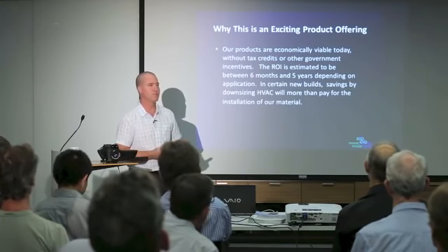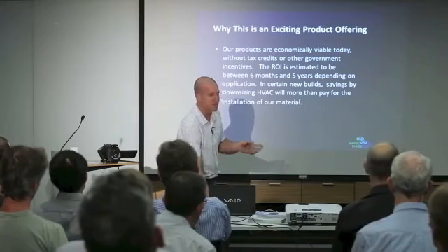This application was a military tent in the desert, and in order to cool the tent to keep the generals cold, they had to have a generator running to run the air conditioner, and it was in a war zone, so diesel was $1,000 a gallon. And the night was 0 degrees and the day was 40 degrees. So straight away you got a perfect situation for phase change to refreeze itself passively and remelt itself during the day. So you get fast payoff, sometimes it's slower.